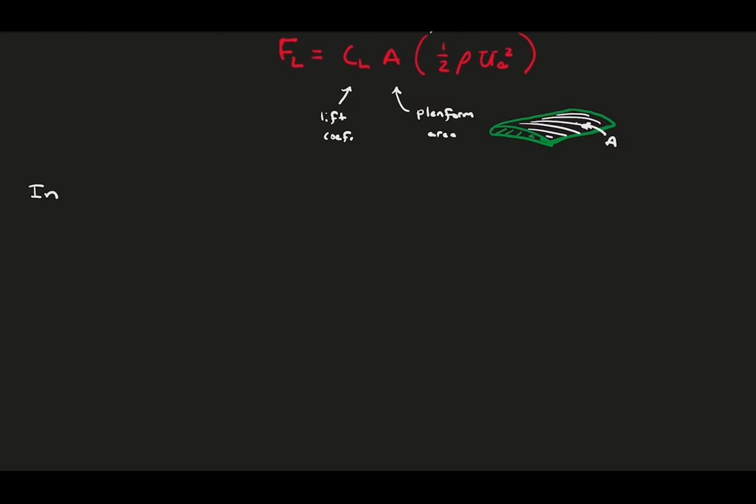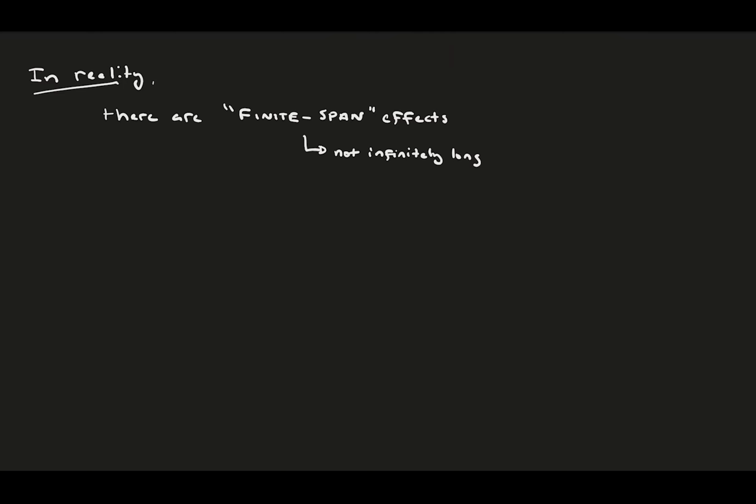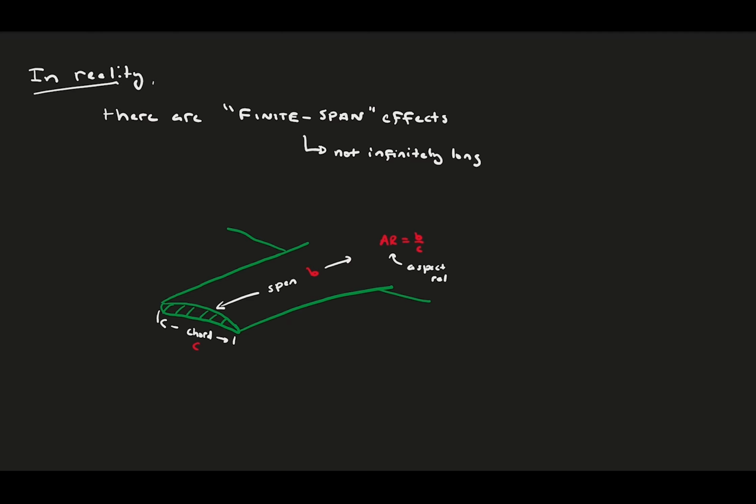Commonly in aerodynamics, we consider an airfoil as two-dimensional and then multiply by some span to get an idealized three-dimensional case. However, most foils do have a finite span, and with that come end effects and losses. For example, consider a finite span foil extending from a fuselage. Here, the foil has some chord and span with the letters C and B respectively. The aspect ratio of the foil is how relatively long it is, which for a simple foil is the ratio of B and C.